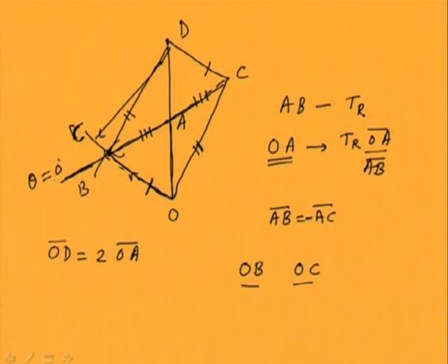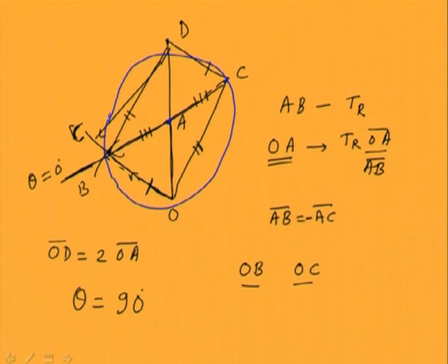For that we need the fourth measurement, that is, corresponding to trial mass at 90 degrees. So for that, let us first draw a circle with the center as A and diameter BC, like this. Now we'll use the fourth measurement, that is OE, and we'll cut it from the center onto the circle. Let us say it cuts here.